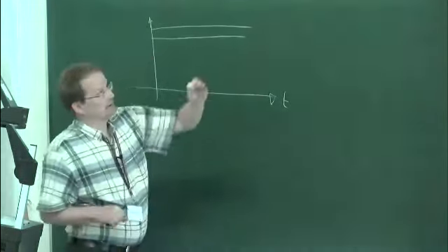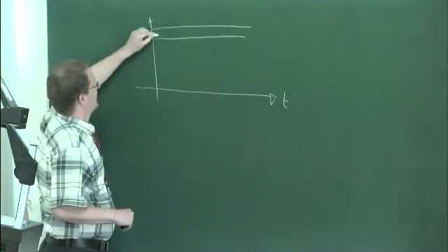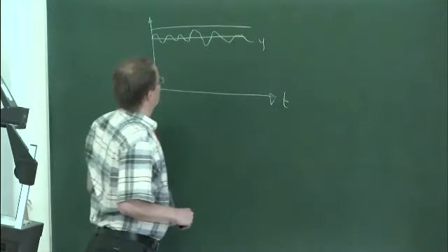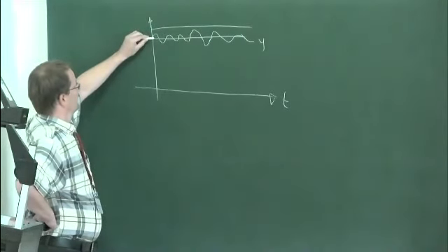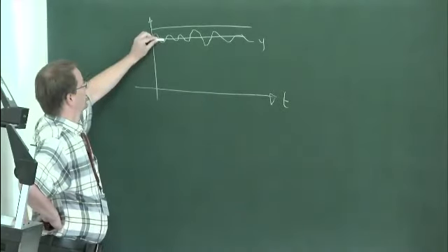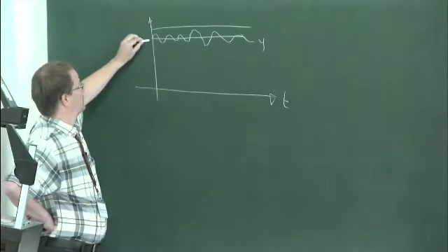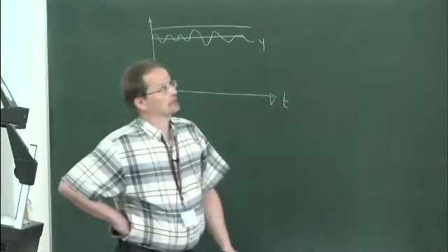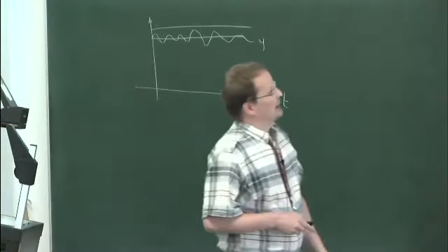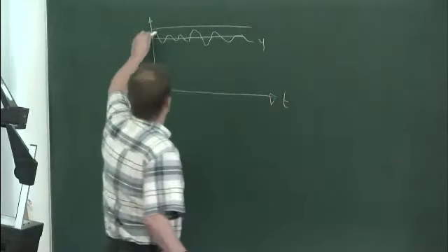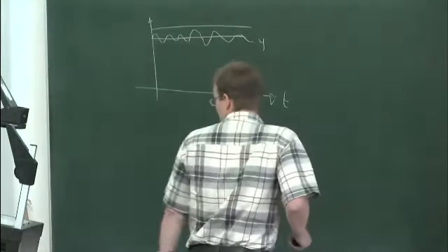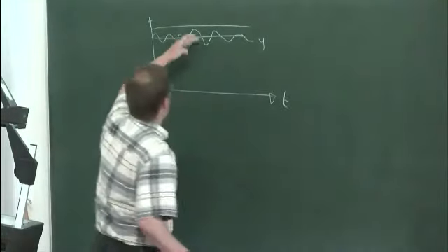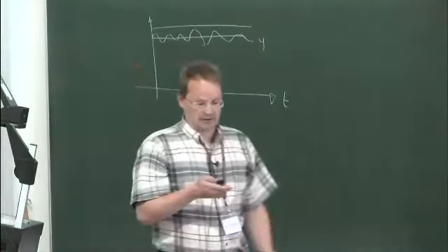But what we consider in the design here is not the set point, it's the variations around the set point. So if this curve here is the output, you see that the smaller variations I have in the output, the closer to the bound I can put the set point and the higher the yield and higher profit. So it's reasonable to just consider the output. In fact, the output power, you could say, or output variance, as a measure. I will use the output energy, which is just, of course, the power scaled by the length of the experiment, so it doesn't really change anything.